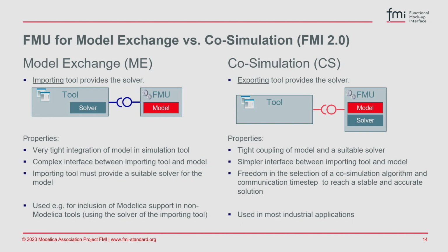So model exchange FMU, as I explained here, the model equations are inside the FMU, and the solution algorithm for these differential equations, this is in the importing tool. And you can imagine that this must fit together. So for example, if you have very stiff equations coming from a hydraulic system or thermodynamic systems, you need here a suitable solver. And that might be a reason why in industry most often co-simulation FMUs are used, because here you can couple them together. So you have, let's say, always a suitable solver for the model.